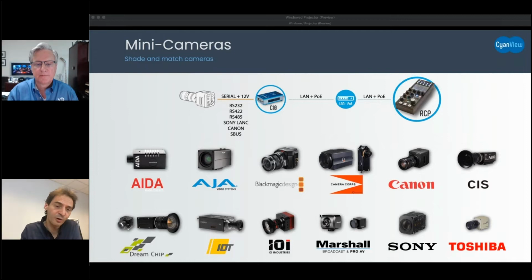Now, if you're controlling it remotely, you plug the cable in, and if you don't answer to the acknowledge of the camera, it will just think that the RCP is not there anymore and comes back to its own control mode. And some of the cameras just change settings completely, so you're losing all the painting that you did with the RCP. Suddenly the iris goes weird and these kinds of things. So definitely controlling cameras locally is what you should start with.